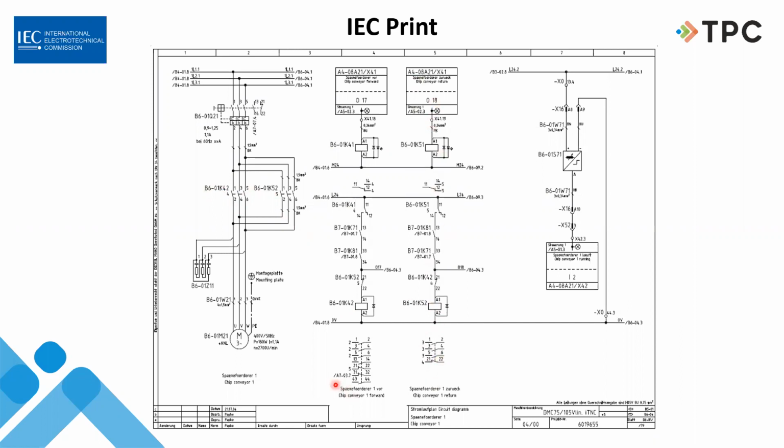And down here, we've got that number that says I've got a set on A7 on a different page. So I've got something else interlocked with it. And so it's important to follow these numbers. These numbers will take you places. And if you notice, every one of these sets of contacts tells us right away if it's a relay contact, because there are two digits right there. This is the second set on this relay. Where this is coming from, okay? In this case, we know where it's coming from, but it's the second set.